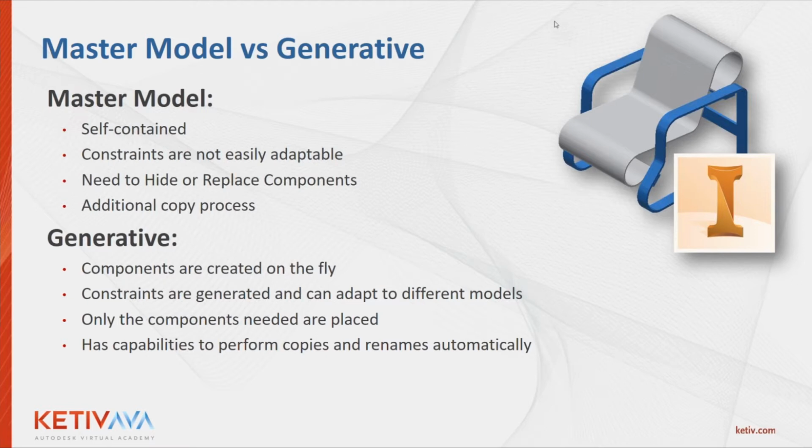But when we start talking about things outside of that scenario, where we need to possibly generate 3 or 4 different designs at the same time, or generate all the options for a catalog or something, it becomes a more arduous process to run iLogic in a master model on all the different master models that you have, and then run it through another copy design process anytime you want to create project-specific instances.